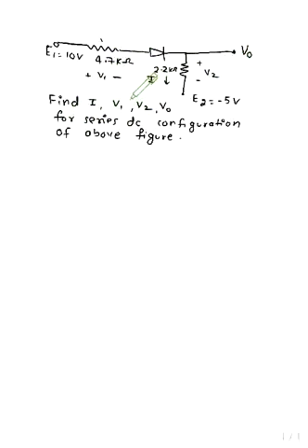For that we assume that the diode is ideal and in forward bias, so we can draw the diagram again. This is the resistance 4.7 kilo ohm, and this diode is a short, a closed switch, and this resistance is 2.2 kilo ohm.